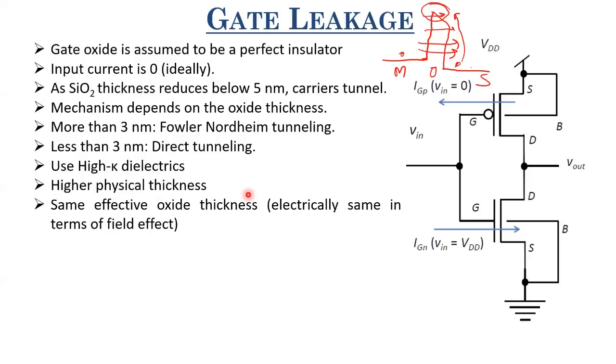However, electrically, the amount of field that it couples remains the same as that thin SiO2. This is something which is hard to digest, but at this time, I would just request you to take my words as they are and try to learn about these high K dielectrics and how they work, if you're interested. But take my words that if you have a capacitor and its dielectric constant is larger than 1, then it couples electric fields better as compared to air.